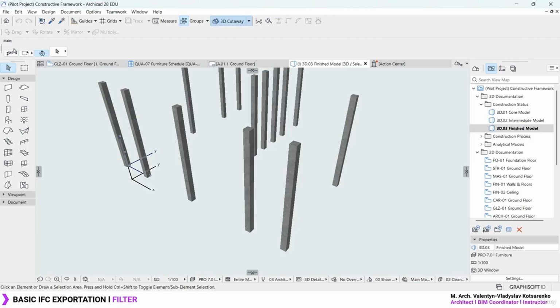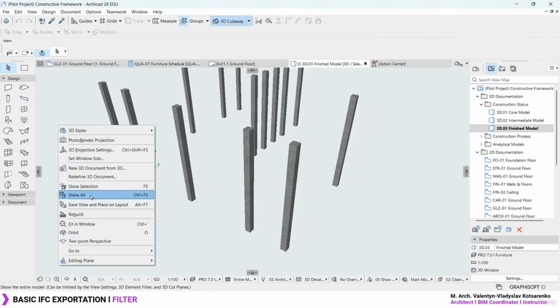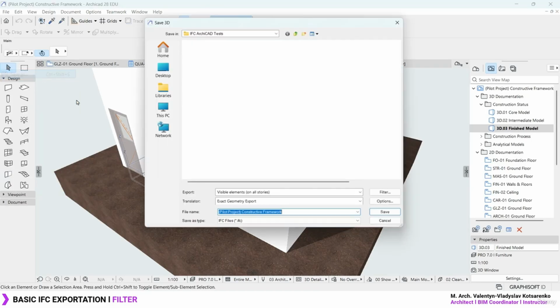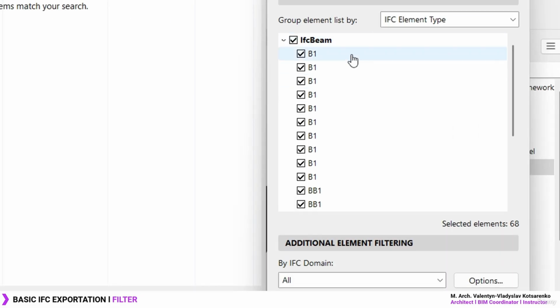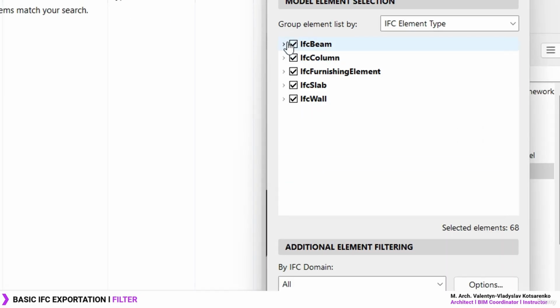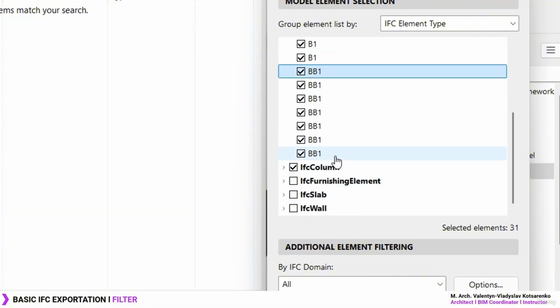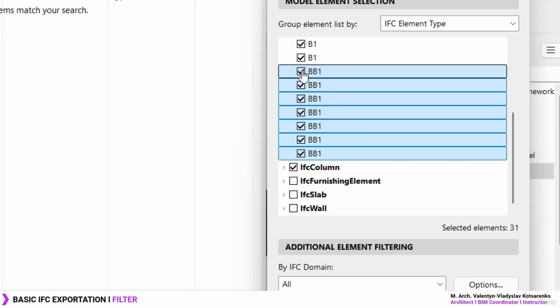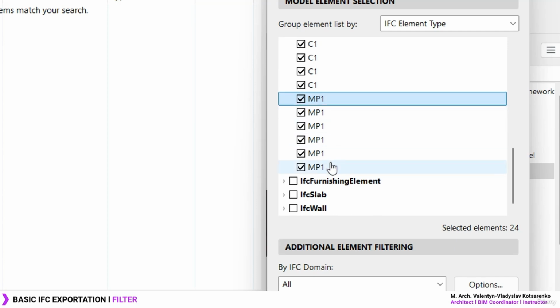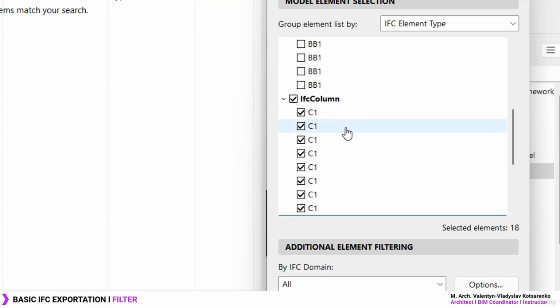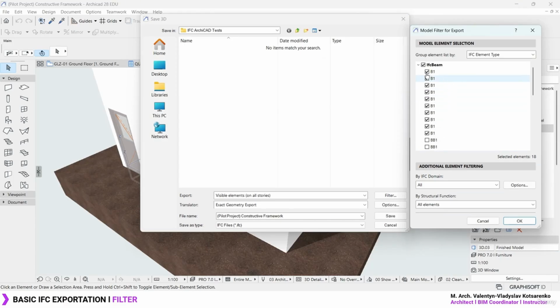So interestingly enough, what we can do is also, for example, filter out specifically which IDs we want to export and which IDs we want to keep. So let's say I want to export only the structural elements in my project. I want to ignore the confinement. So for example, you can hold down left shift, deactivate the confinement elements. You can identify by the ID and it's going to export only the selected elements. So that's quite an amazing opportunity you get in the exportation, okay?